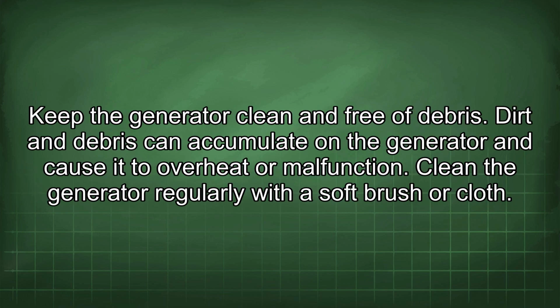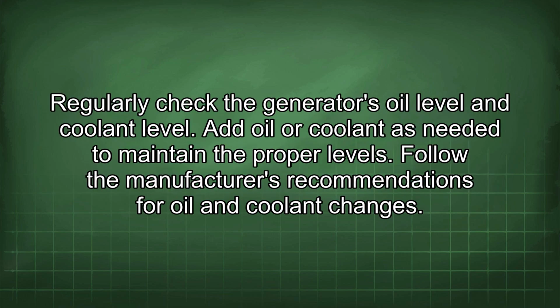Keep the generator clean and free of debris. Dirt and debris can accumulate on the generator and cause it to overheat or malfunction. Clean the generator regularly with a soft brush or cloth. Regularly check the generator's oil level and coolant level. Add oil or coolant as needed to maintain the proper levels. Follow the manufacturer's recommendations for oil and coolant changes.